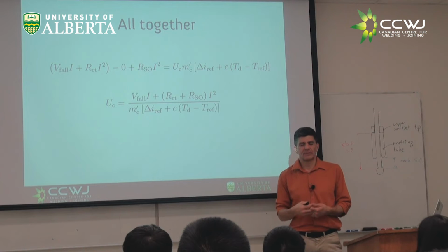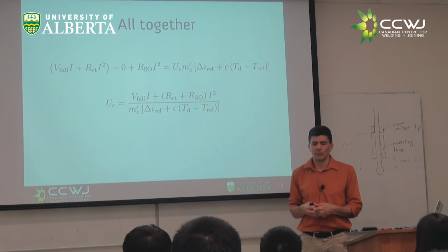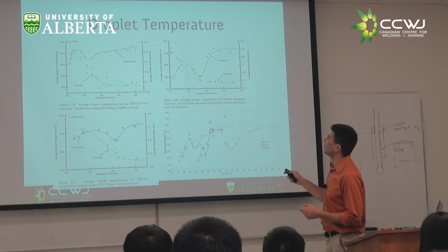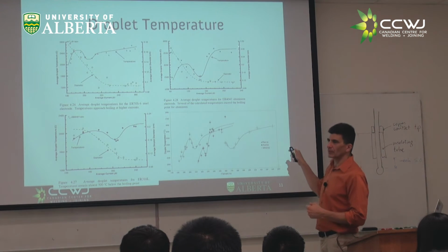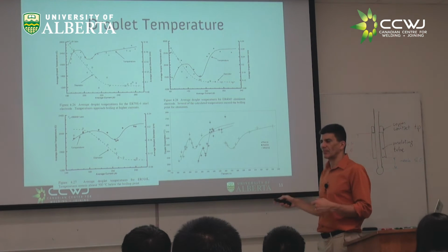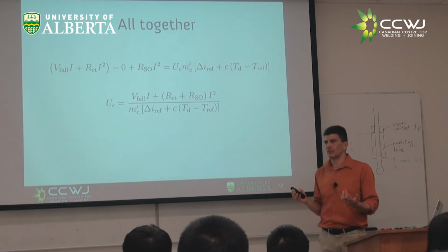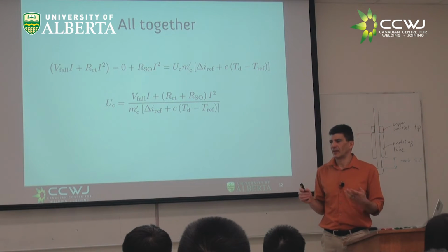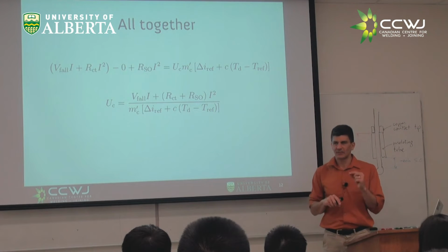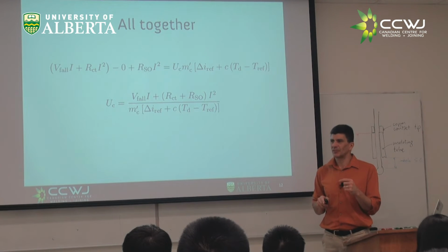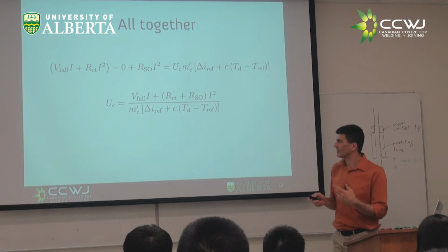So, for example, when we go through these variations in temperature, right, we actually see a change in wire feed speed. In these curves I showed you from Lincoln from the 70s, they just put a curve tracer because it's a subtle change. But you get to see those things, right?